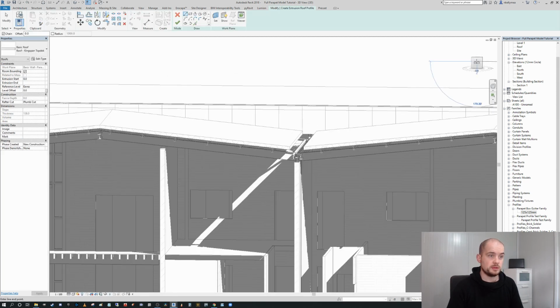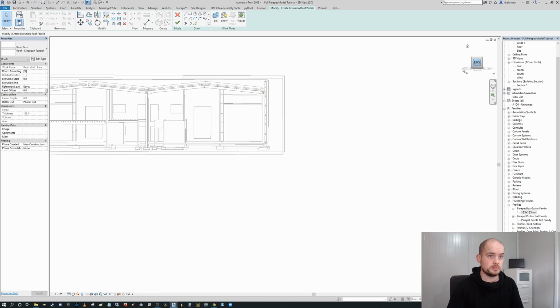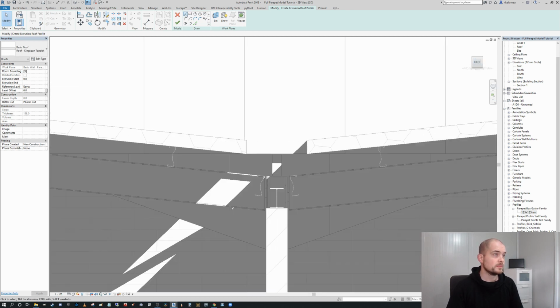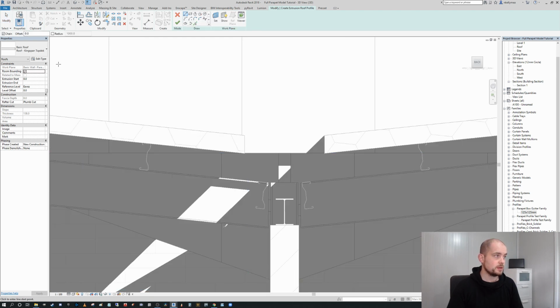And now I'm going to draw the profile which we want, okay? So in this instance, I'm going to change it from Topdek to mid gutter, because that's a roof construction I previously developed. And what we're going to do is take this down approximately 45 mil.